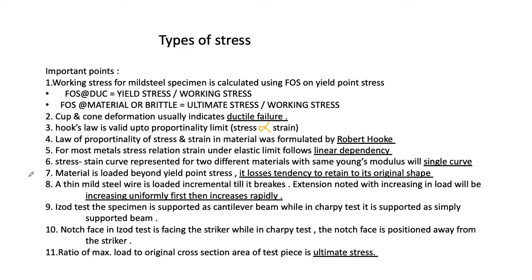Up to the proportionality limit, stress is directly proportional to the strain. The law of proportionality of stress and strain in the material was formulated by Robert Hooke. For most materials, stress and strain under the elastic limit follow a linear dependency. When a material is loaded beyond the yield point stress, it loses its tendency to retain its original shape.